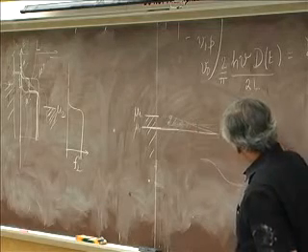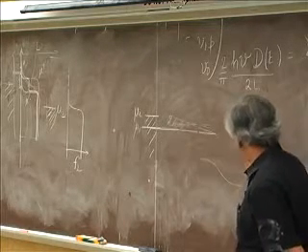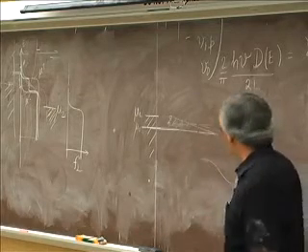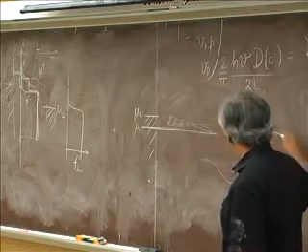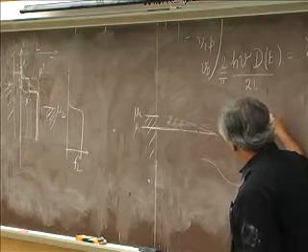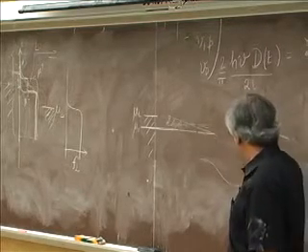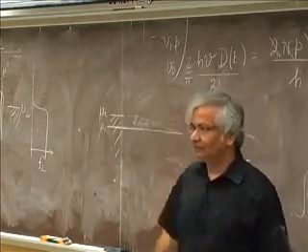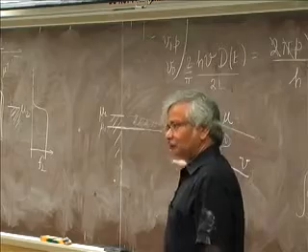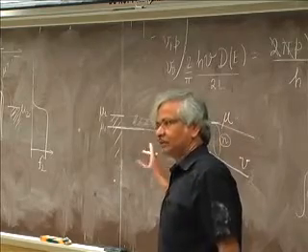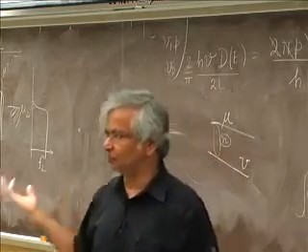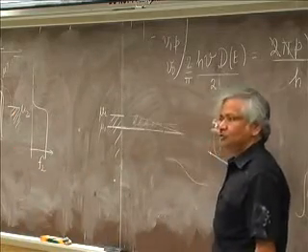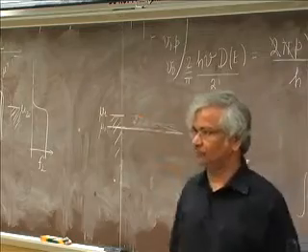Right. But the picture I have also, yeah, this is the mu, that's the U, and the electron density is proportional to that. And the point I tried to make is that current is really determined by the slope of this one, which you can break up into the slope of this and the slope of that. And then one is drift, one is diffusion, etc. But to me, that's a derived secondary step that under certain conditions may be useful. But to me, always the starting point is current is proportional to derivative of the quasi-Fermi level.